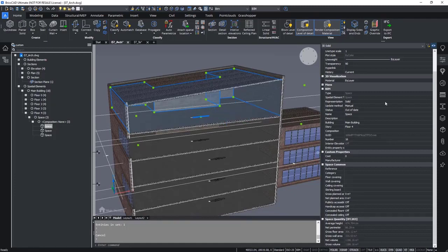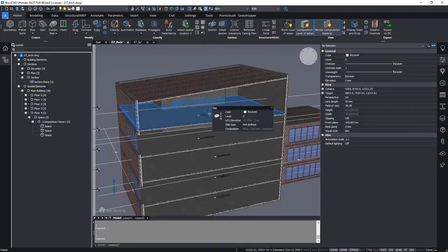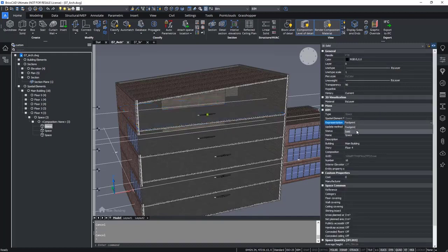And if something would be wrong, you can see it because the space will not occupy maybe the entire room. But here everything is correctly done by BIMify, and you can see that you can switch between the representations easily. While you're editing your BIM model and you don't need the spaces, I recommend to put it on footprint, as it doesn't get in the way of selecting slabs, etc. If you have it as a solid representation, it might get in your way to select the slabs underneath.